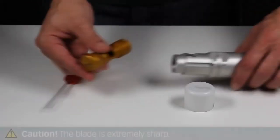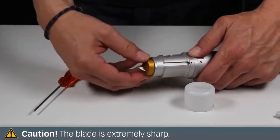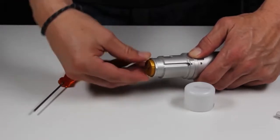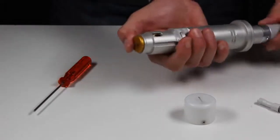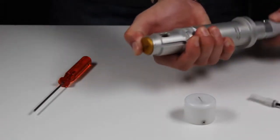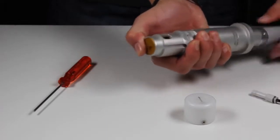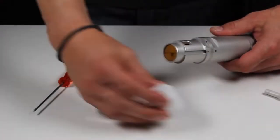Now we can insert the blade holder into the SCT. Activate the stop and move the blade holder into the tool guide. Press the blade holder into the guide and turn the height adjustment. Carefully attach the slipper.